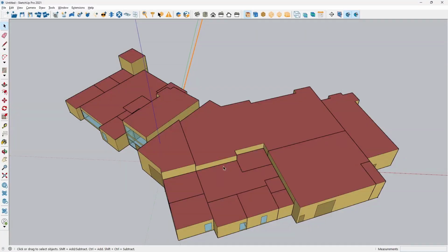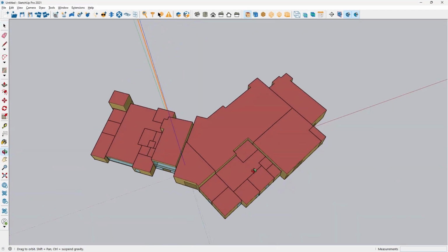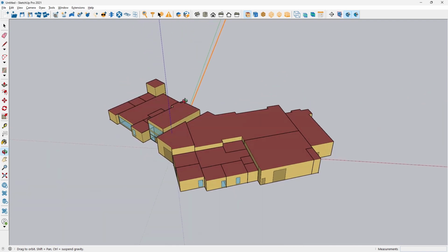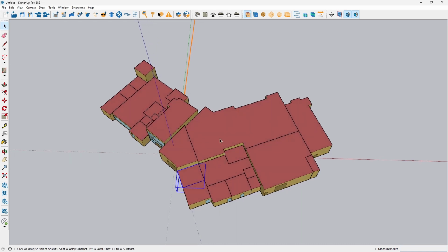And if you take a look at our building right here, you can see that there's a lot of spaces here, but all of these spaces are actually grouped into only one thermal zone. All of these spaces get combined into one big thermal zone, and they get passed to EnergyPlus as a single thermal zone.